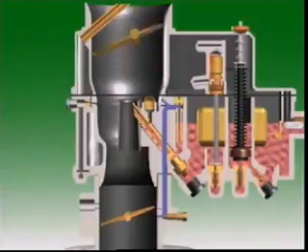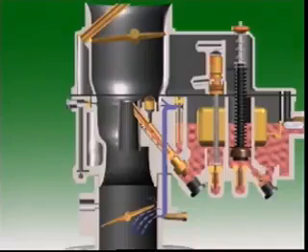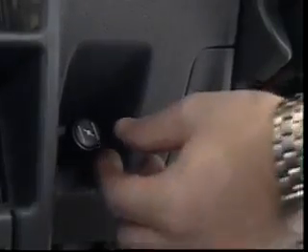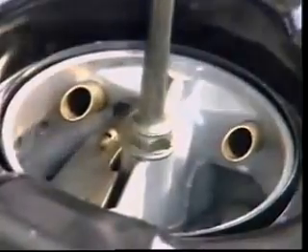Closing the choke valve closes the carburetor intake. The pumping action of the pistons creates a low pressure area below the valve even without venturi action. This low pressure causes fuel to flow from the discharge nozzle and from the idle and low speed ports, and provides the rich mixture needed to start the cold engine. The choke can be controlled manually by a cable that operates the valve.